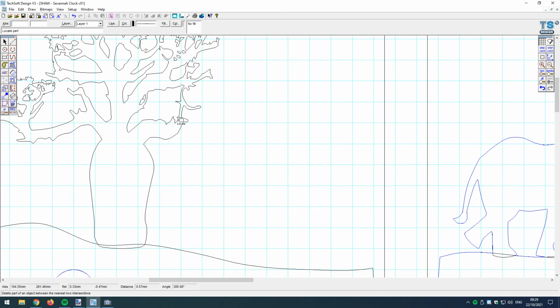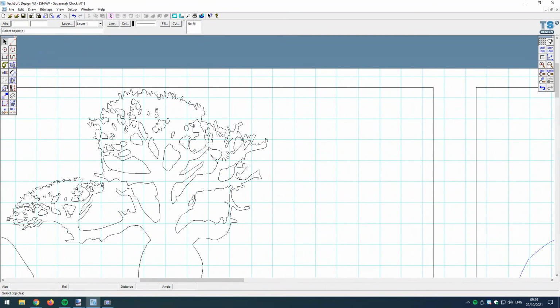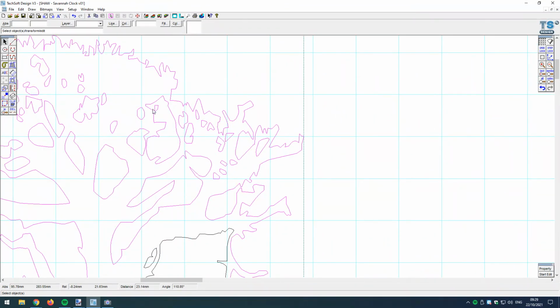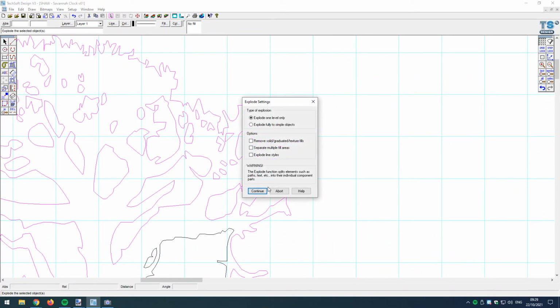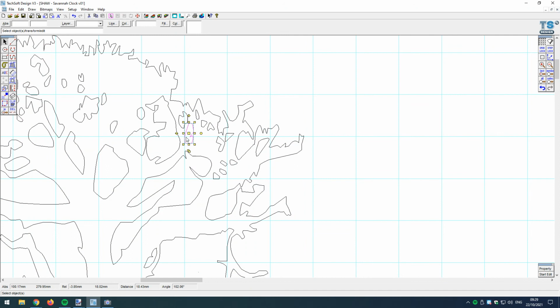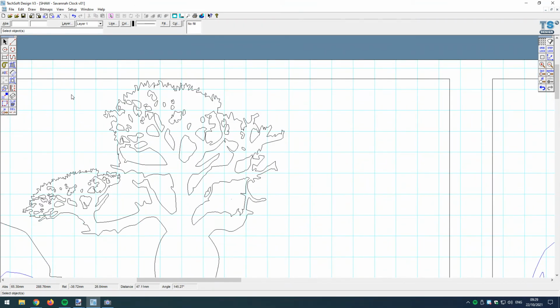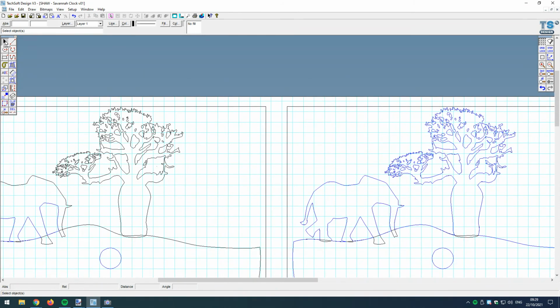And use that same technique to get rid of this section here as well, so this just stretches out and stops. I could look at selecting some elements here, or I could explode this. Let's just try and explode this again. Control E, explode it. Then I could get the selection tool and delete some of these little points that are causing me a problem, and just keep a few of them that I think are appropriate, like this.